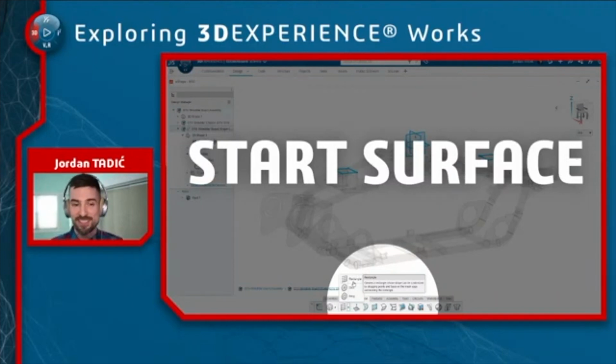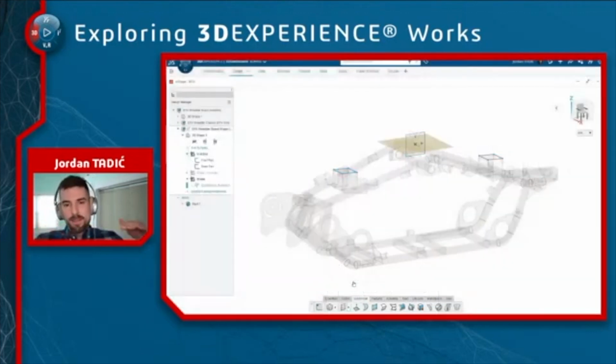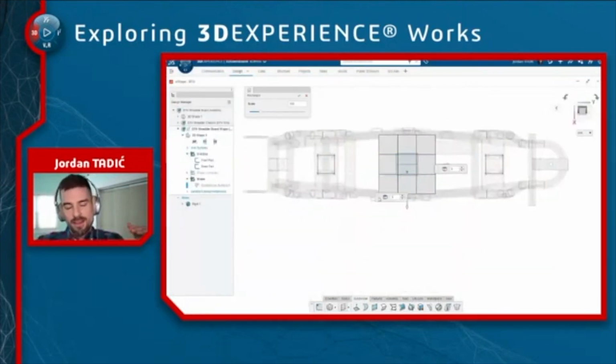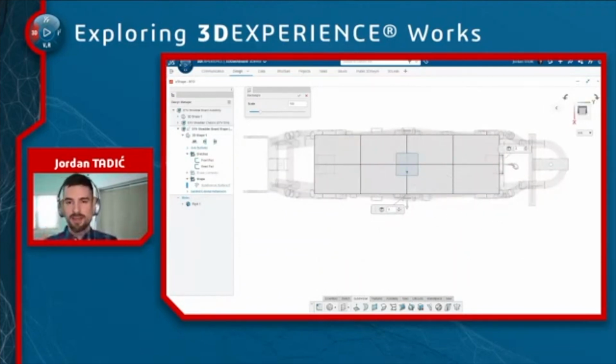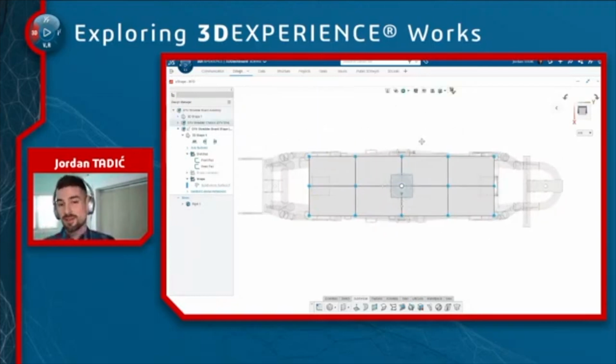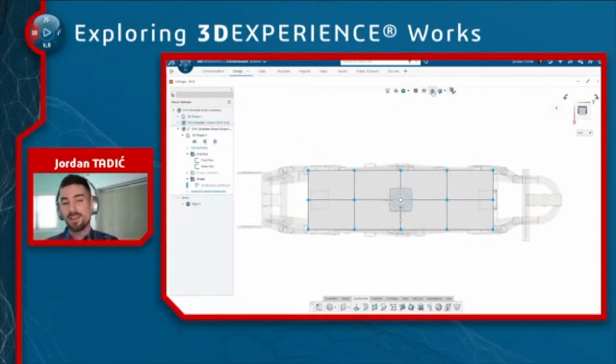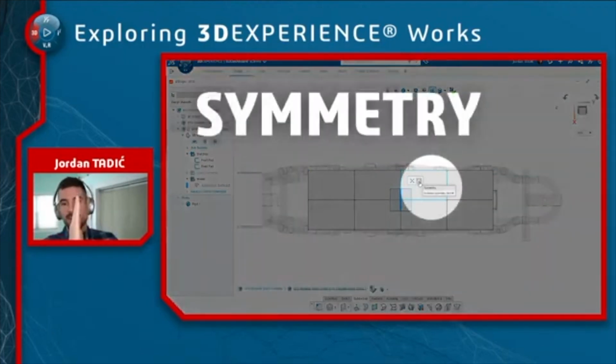A surface is what we're starting with here, because for the most part, this board is a thin design. And when I'm picking subdivisions again, my mind is going to, hey, I'm going to make this symmetrical, so I want an even number of subdivisions. So I have a bisecting line down the top plane and the side plane that I can provoke symmetry around.